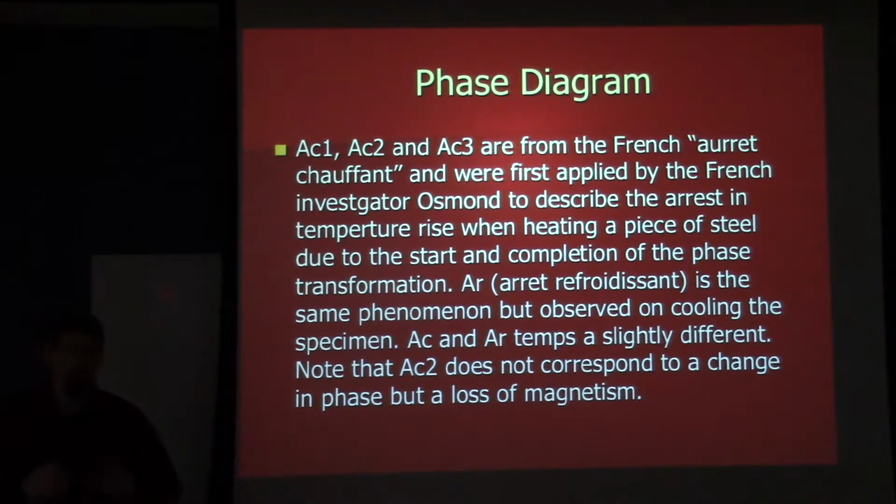And so if you are reading an old blacksmithing textbook or watching somebody do a demonstration, you may see that they go to heat treat a tool, they want to make sure that they've fully austenitized it. They'll use a magnet to test when the item they're working on has lost its magnetism. That's a pretty decent gauge, but you might find that it's not exactly correct if you were able to compare to one of our more precise measuring methods.